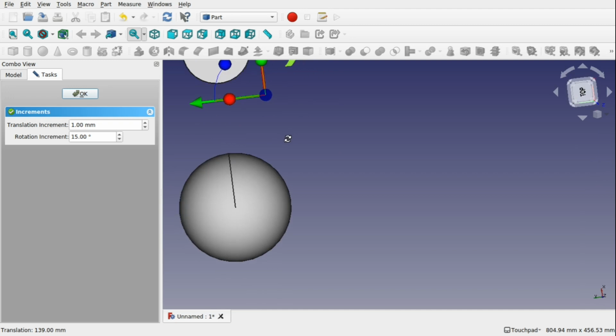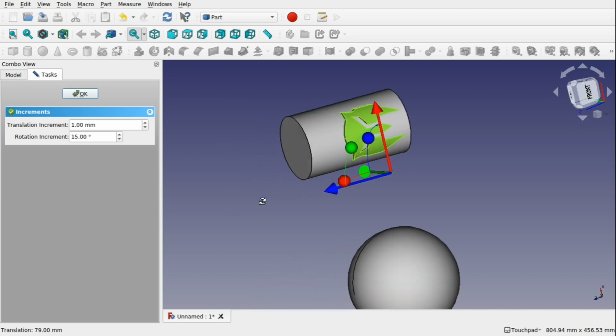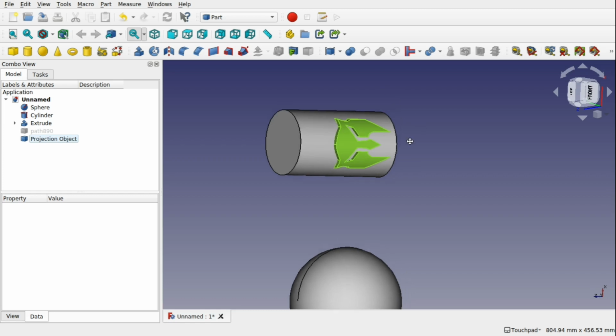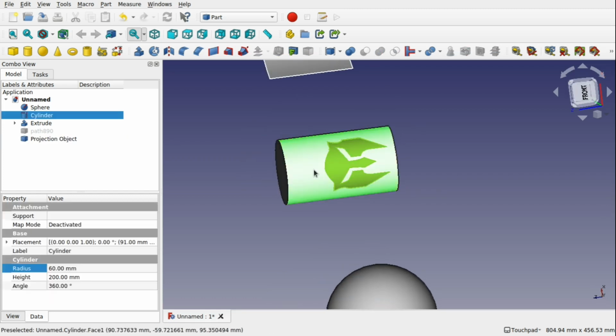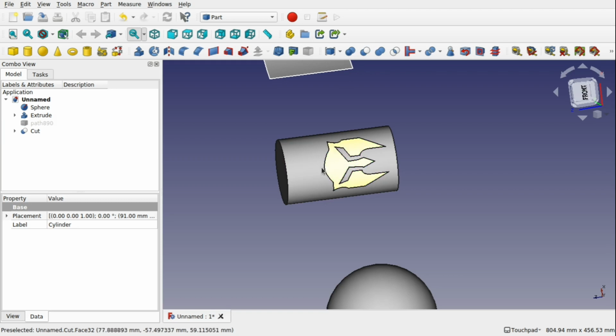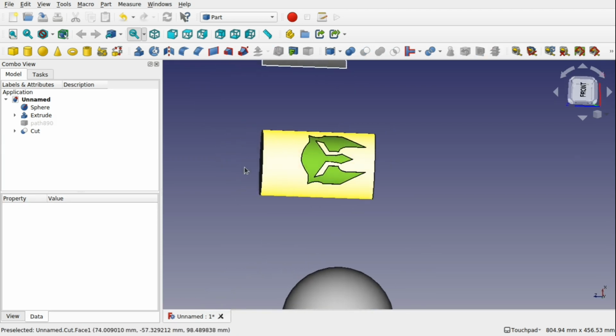And also, I can get it back into position like that. Hit OK. And we can take that surface, cylinder, Ctrl-click this one, and you've got your Boolean operations here if you so desire. So I've just inset it into there like so.